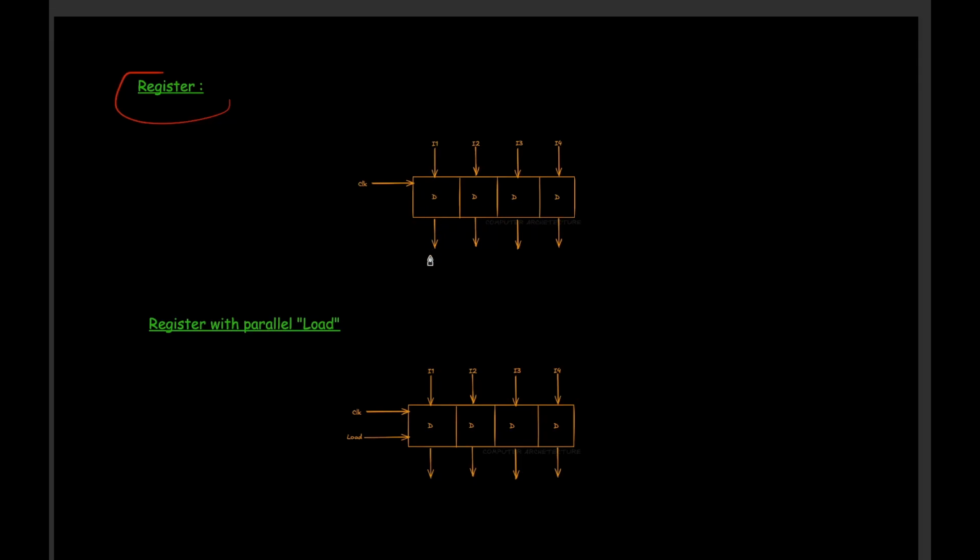So whatever the output of the D flip-flop, let's say the output was 0 and the input is 1, and the clock was 0 initially. Whenever it goes from 0 to 1, this is a positive clock, so going 0 to 1, the output will also become 1.